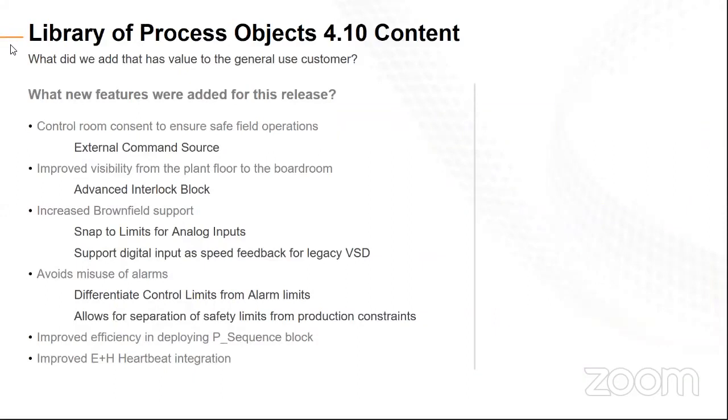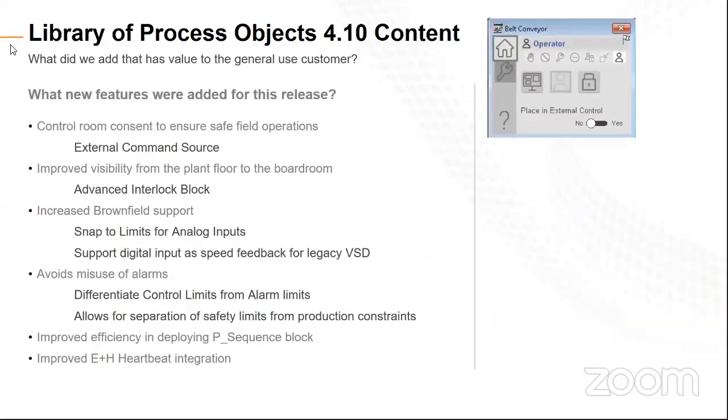You want to talk to the objects a little bit? Yeah, so we did release a new set of library objects. The question that we usually get when it comes to PlantPAx is, for a PlantPAx system, do you need to use the process library objects? The answer is no. Obviously, we did separate those out. But if you look at all of our documentation, we heavily use the process objects as part of our sizing utilities, how we do the HMI system, how we tie in with all of the tools. So if you want your life easier, you use the library objects, but they are not required.